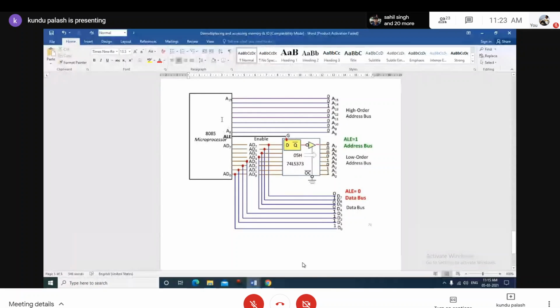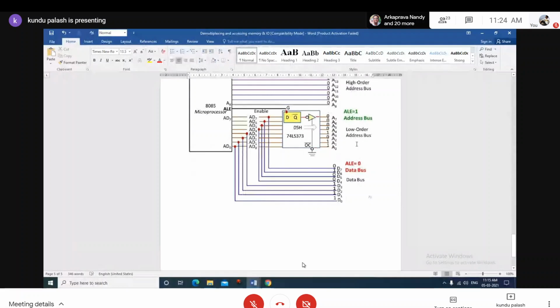So that's why the 8085 and Intel CPUs generally use this method of multiplexing the address and the data bus into a common bus signal. Similarly, there is an essential need for demultiplexing the address data information. Otherwise, the information about the address and the data bus will be mixed up. How will the memory location be uniquely addressed with the help of a unique signal? This is not possible without demultiplexing. So because the 8085 CPU generates the multiplexed address data information, there is a need to use an external demultiplexer, that is a latch, to separate the signal over two separate 8-bit lines.